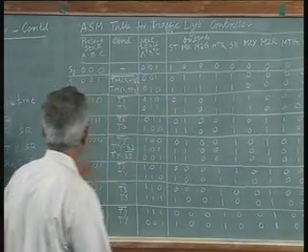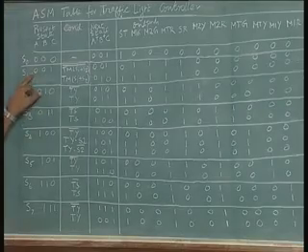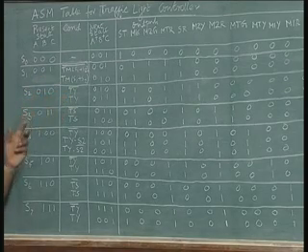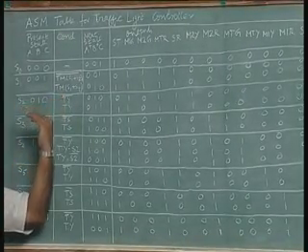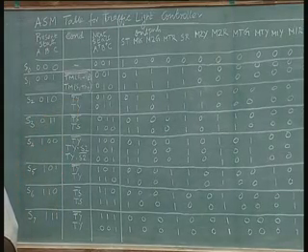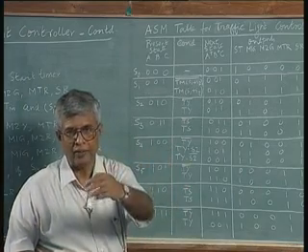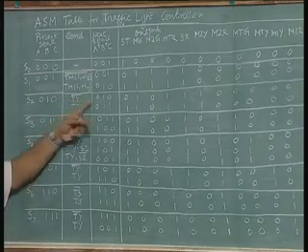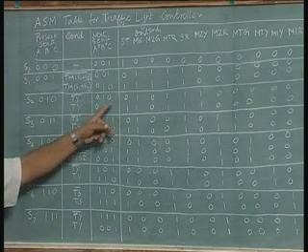For example, you can see in state 1, or make it a simpler state, state 2 which is 0 1 0, all we are looking at is yellow. This is main 2 yellow, M2 yellow. M2 yellow we are allowing for the yellow time to be over before we turn it off to red, so that we can allow the side traffic, main traffic to side road. So that is the condition here. If it is not there, you continue to be in this state. After that you go to the next state, and so the lights are correspondingly marked here.